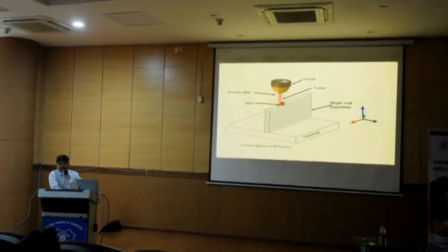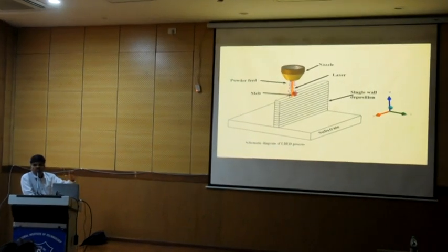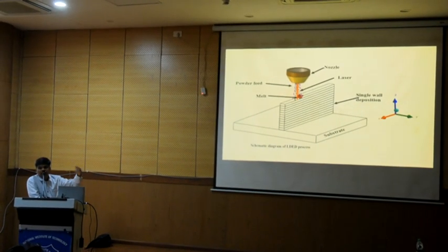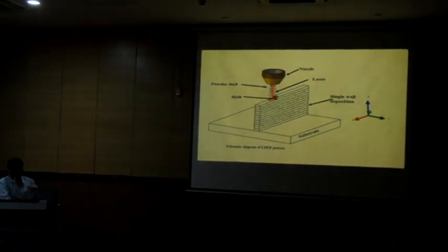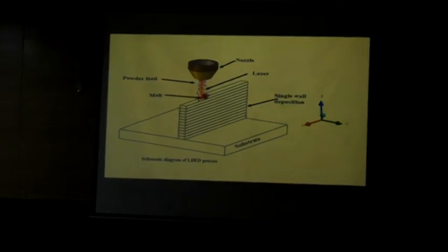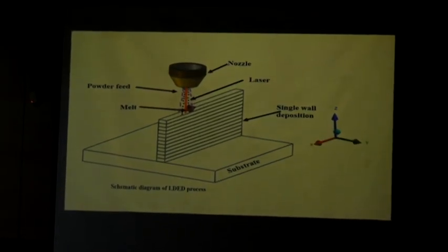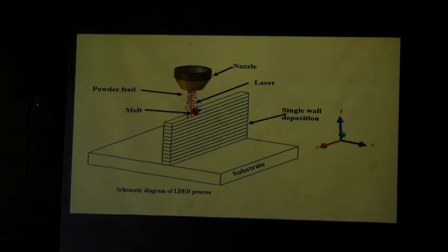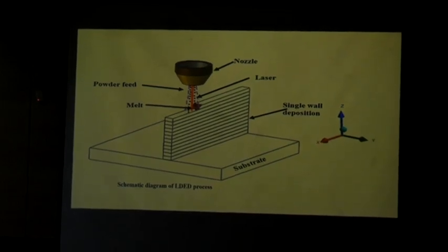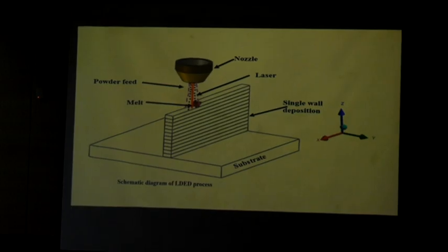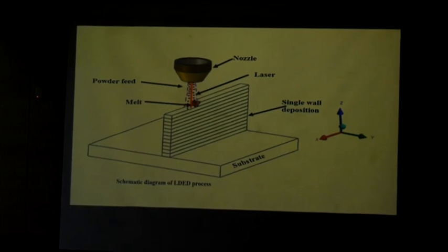Like one of my master's students last year performed this experiment. We wanted to fabricate thin-wall structures. As I showed you in the video, it accumulates heat. But for a single layer, how does solidification take place, and if I go for multiple layers, how does heat accumulation take place, and what about the stresses at different locations? These things we can understand numerically. This gives some idea of what range we need to choose the process conditions in for fabricating our component.